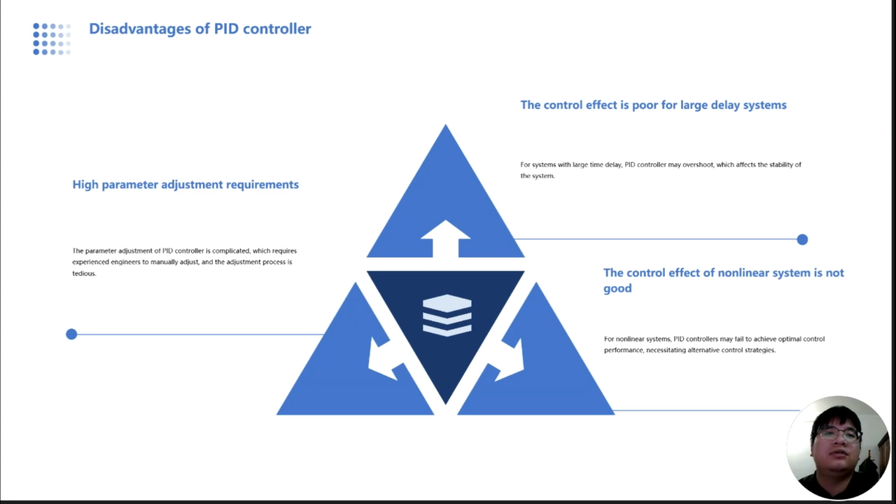Secondly, there are also limitations in dealing with non-linear systems. For complex systems with non-linear characteristics, fixed PID parameters are difficult to achieve optimal performance at all operating points.